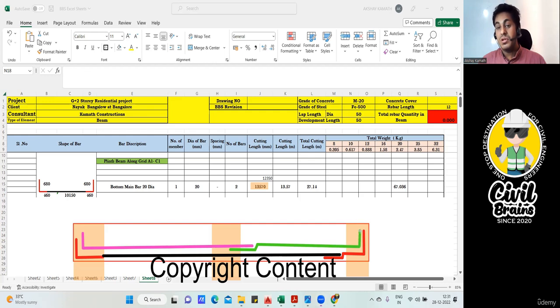See, there is a lot of difference between doing it on paper and doing it on the site. On paper I got 13.570, this much steel is required. But from the execution point, you need to plan accordingly. Execution will be done in this way. You'll bring one bar which will go straight up to here. Let us say this is a 12 meter bar, and you'll cut it like this and bring. So this will be your 680, this is 460 and this is 10,180. By the time it reaches here, one complete bar has ended.